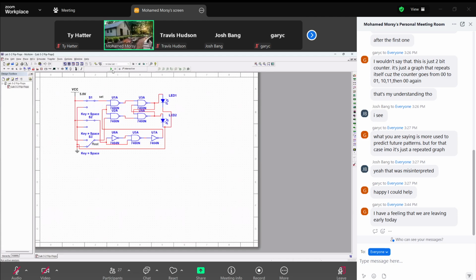The output depends on the two inputs, S and R. So what do you mean by very fast? When you connect this, S is 1, R is 0, so output is 1. And it stays until you change the input.